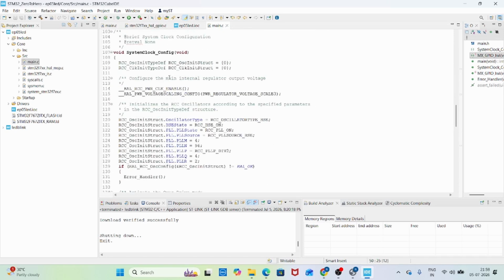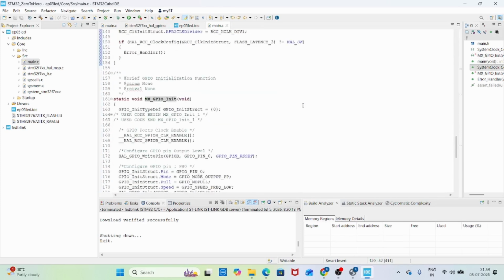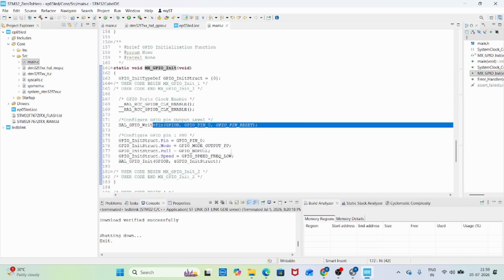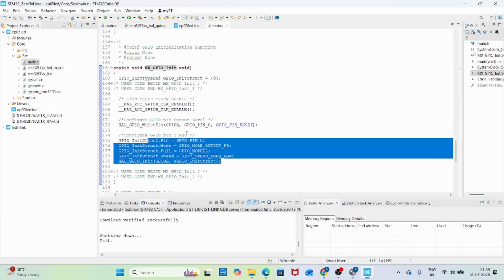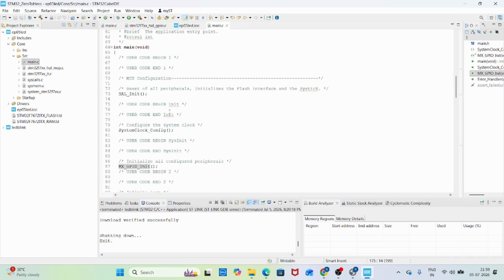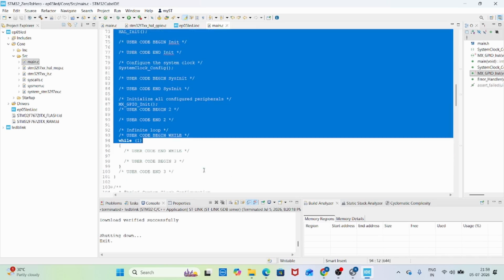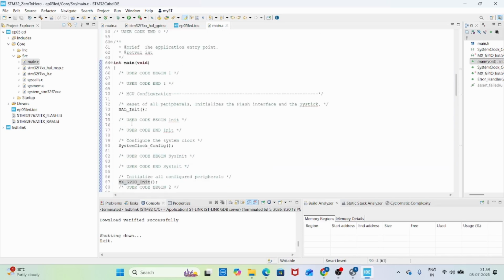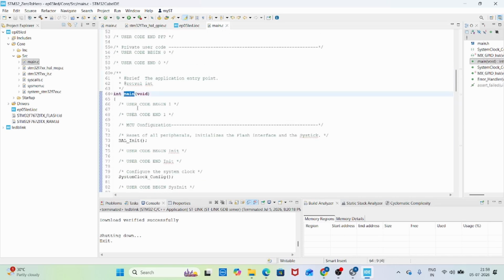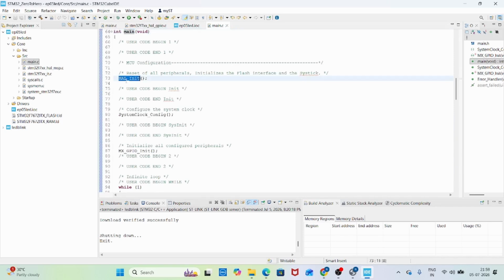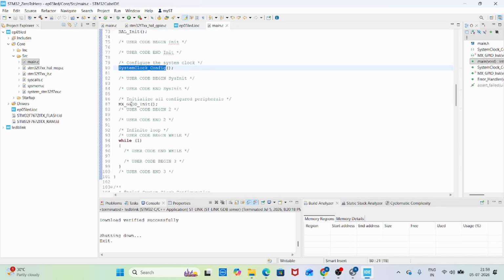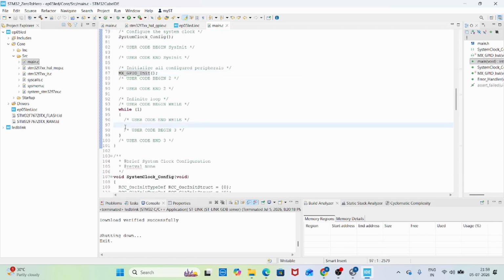And if you see the system clock, based on our selection, the clock is there. In GPIO you can see PB0 reset. So by default this pin is now enabled and set as an output, so we can use it. Everything is there. Our job is to simply write this main function. Now here while(1) is blank. So this is a simple C program. You can see from void main to HAL_Init, it will initialize the required functionality, system clock, and GPIO. Now here we have to write the code.